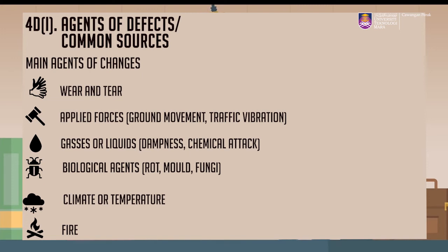In a severe fire, the temperature may rapidly increase within a short period of time. The concrete of the building structure will be damaged. The failure could occur from loss of bending or tensile strength, loss of bond strength, loss of shear strength, and so on.